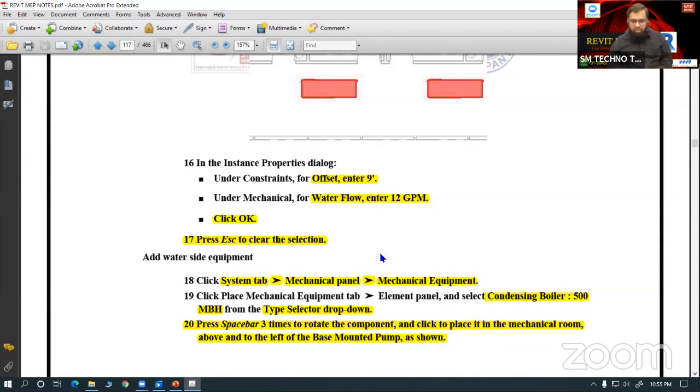But plumbing and firefighting design is based on probability, no? So even though the pipe sizer is available in the Revit software, we cannot use that pipe sizer for plumbing and firefighting. That can be used only for HVAC. But Revit offers you the total fixture unit for plumbing, for water size as well as for the drainage side. Using that, we can confirm the pipe size with the Excel program, how we deal in actual practice. The branch pipe is directly connected as per the fixture. For the main pipe, you'll get the total fixture unit. That will be helpful to confirm the main pipe size. But directly you'll not get the pipe sizer for plumbing and firefighting in Revit.